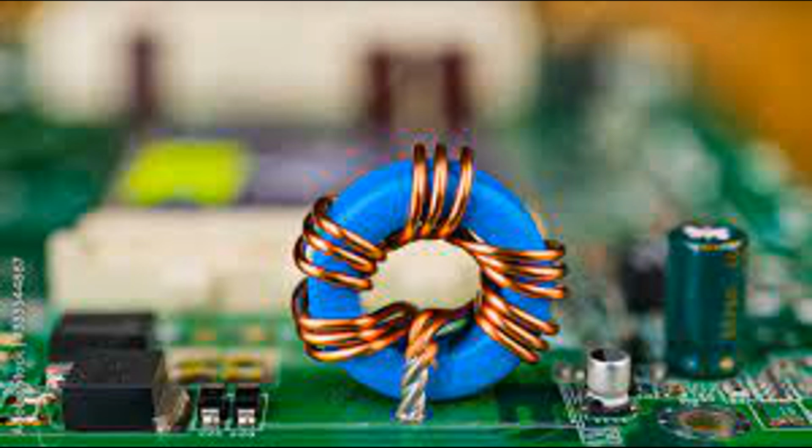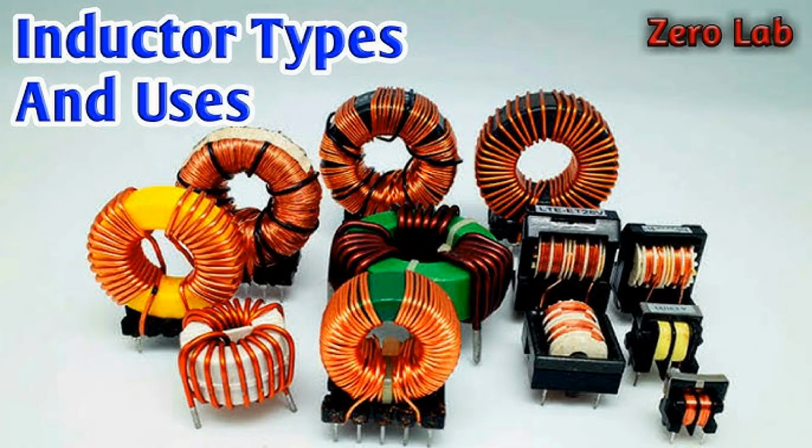Key points. Mutual induction. The varying current in the primary coil induces a corresponding voltage in the secondary coil due to the shared magnetic field. Efficiency. Transformers can transfer energy with very high efficiency, often above 95%, making them ideal for large-scale power transmission. Voltage transformation. By adjusting the ratio of turns between the primary and secondary coils, transformers can increase (step up) or decrease (step down) the voltage. Applications of energy transfer in transformers.